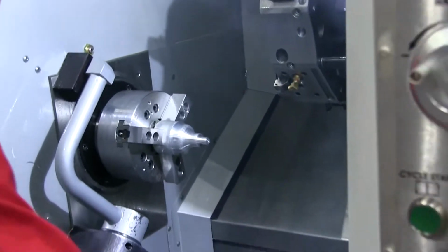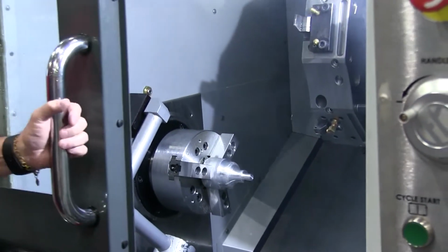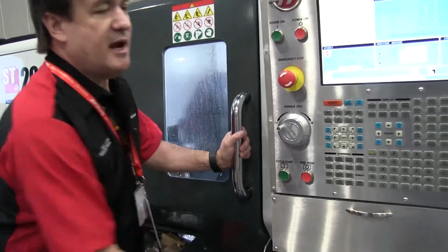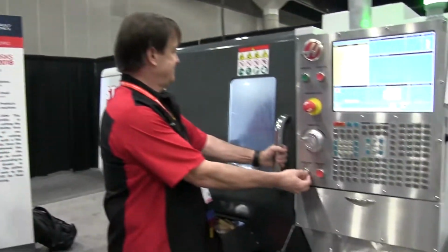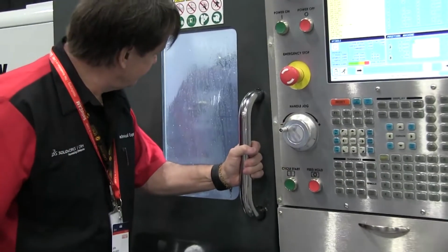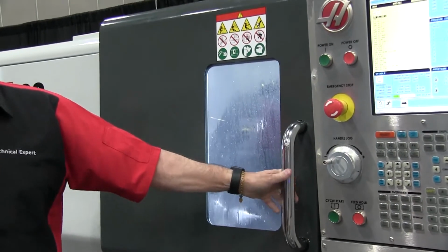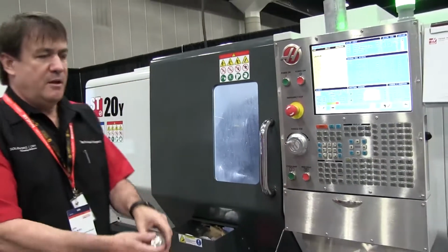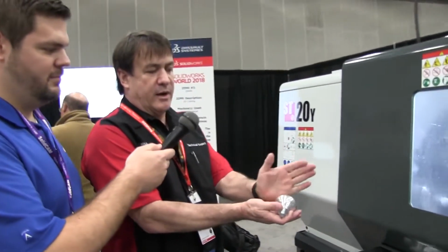Wow, that's remarkable. So let's go ahead and do a little bit more work on it. Okay. The entire process takes about 2 minutes to complete one of these. Okay. This is going to require a lot of room to clear a finishing tool. So what I'm doing is putting a huge groove chamfer behind the back of it so that I can fit a finishing tool in here.